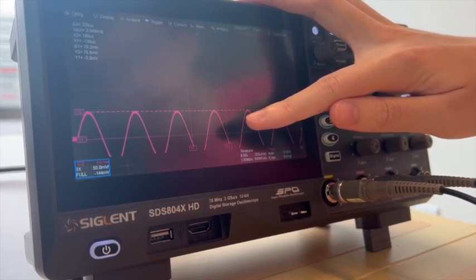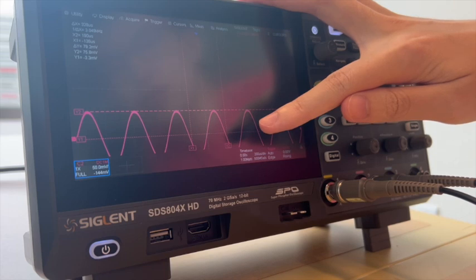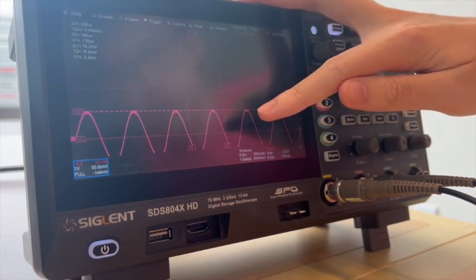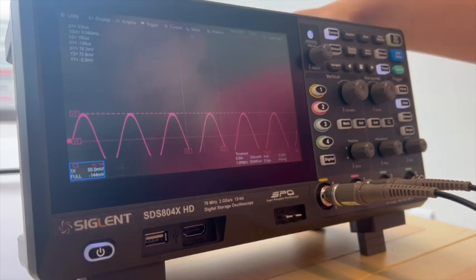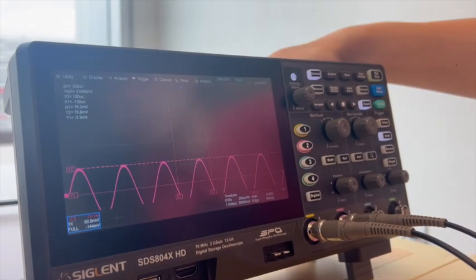And if you're looking for your AC offset, that is your sinusoid. If you're looking for your AC voltage or RMS voltage from your multimeter, then you'll just want to use your multimeter, hook it up like a normal multimeter, which I'm sure you know how to use by now. And then from there, you will just measure your RMS value and then record that in the table.